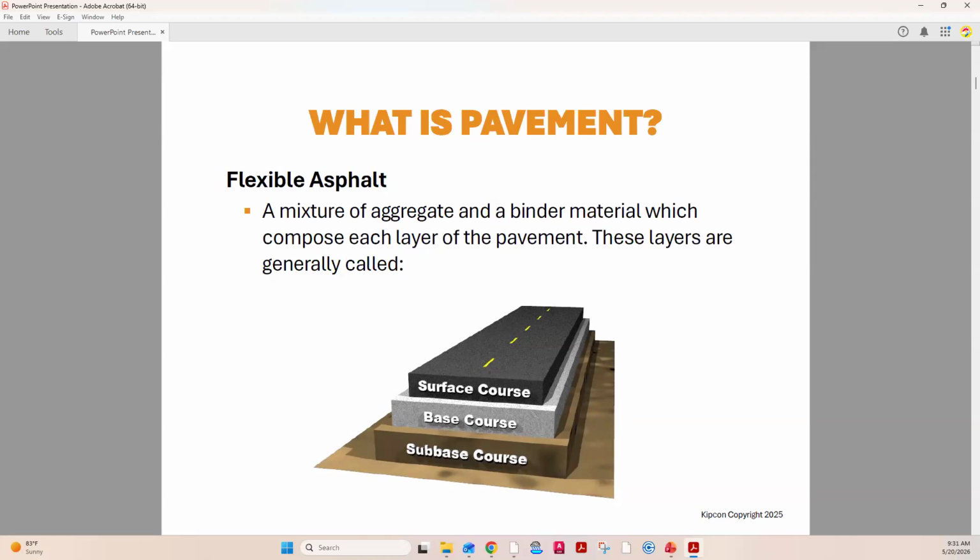This type of pavement that we're talking about today is flexible asphalt. It is impervious. It's constructed in several layers. So when the community is new or when you're putting down a new roadway, no matter where it is, when you're constructing an impervious asphalt, you put down first a subbase that lays on top of the native soil. It's usually an aggregate course, meaning that it's made up of loose stone or stone that can be compacted.